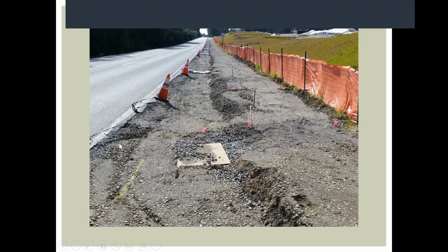Another example of that, you've probably all seen steel plates on projects and know that that's covering an open hole, like a manhole. So the first question to ask when you go on site and you see a catch basin is, is this a live system? Is this hooked up yet? Is it hooked up to on-site stormwater systems? Is it hooked up to existing city or county systems? And know that all the clean water that's draining off the asphalt, draining down through the dirt here, is going into this catch basin or this hole, and it's going somewhere.